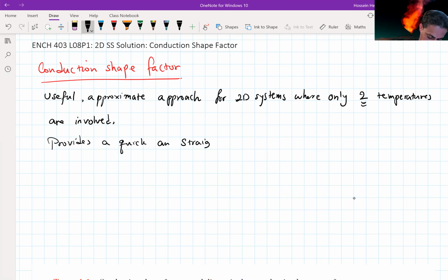With this assumption, we can use the general form that we set for conduction, which is going to be k of soil, the shape factor, and the temperature difference from the hot to the cold environment, T1 minus T2. Now for this geometry, we can find the shape factor. If we come to this table, this is case 2, and it has two restrictions.